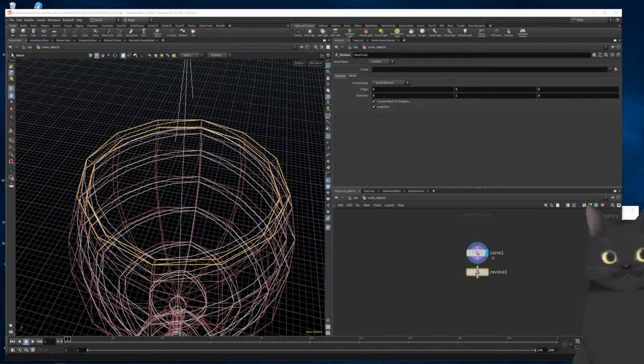Double click, and then press the shift key and double click two more edges here and here. Double click. And we're going to take these particular edges and we're going to go tab and then crease. Start typing crease. Press enter, and we're going to crease those edges. So that means when we subdivide, those edges will stay relatively sharp. Now if we went up to 10, they'd be completely